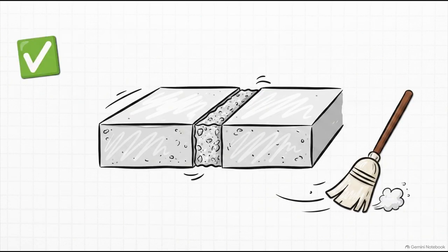Well, you have to step in right away and verify the condition. Ask yourself, does this surface still qualify for a wet-on-wet continuation? No way. Because it's partially hardened and dusty, it has officially crossed the line. It must be treated as a hardened intermediate surface and fully prepped before they can continue.